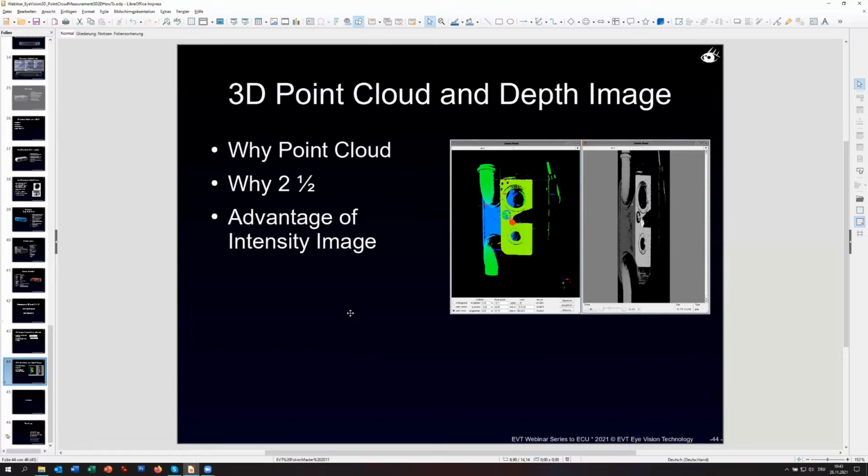Dot code means, if you know tires, you have these letters on the side, which are in 3D. So the intensity image wouldn't give you any information about these prints because it's black on black. But the Z value will generate height information, and in that case, you have a contrast. Let's name this Z delta information as contrast, and at the end, then you can read it.